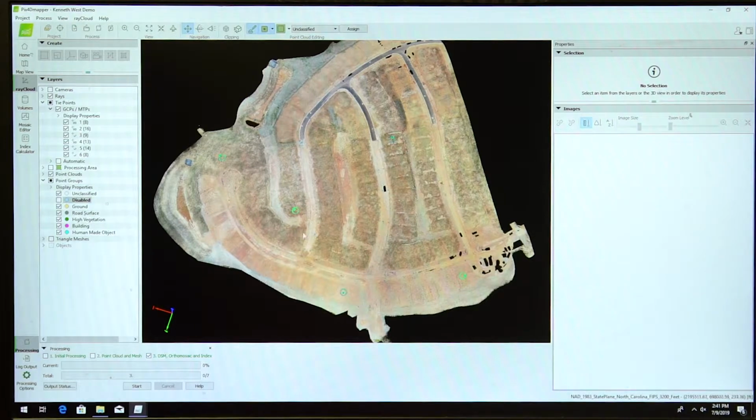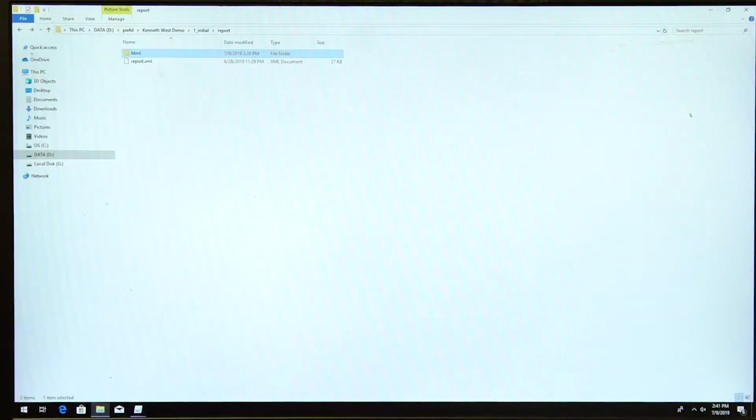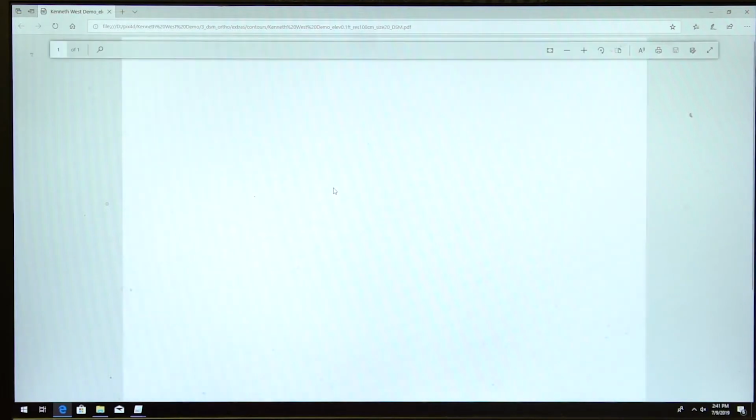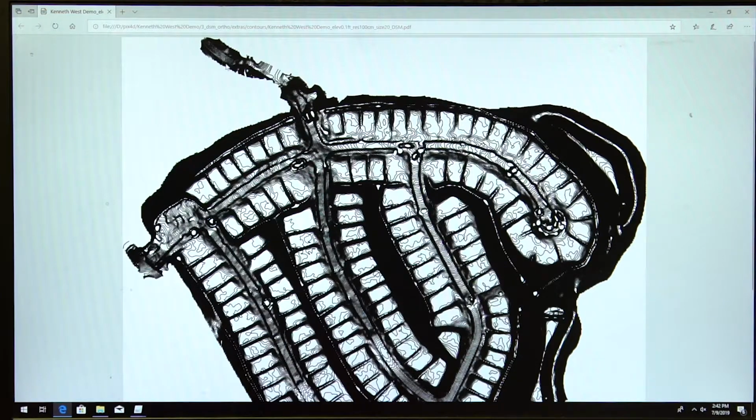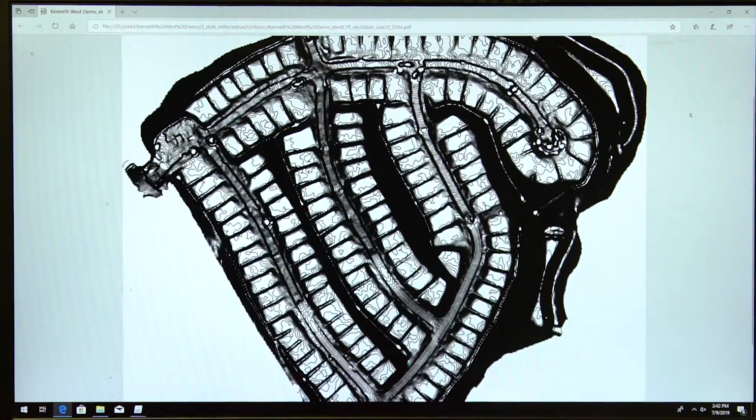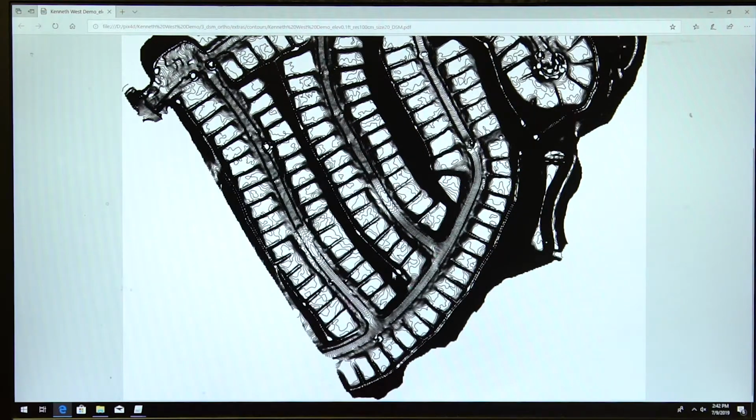After step 3 is done, you will get a file. If you go back into your P4 file, your job site file name, and go into 3D Ortho, you go into the extras buttons here. This is where your contour files are stored. I'll open up the PDF so you can see what the PDF version of that site contour files looks like. And you can see from this file at 1/10 of a foot, you get a lot of contour lines, so you can build an accurate surface off of this contour file.